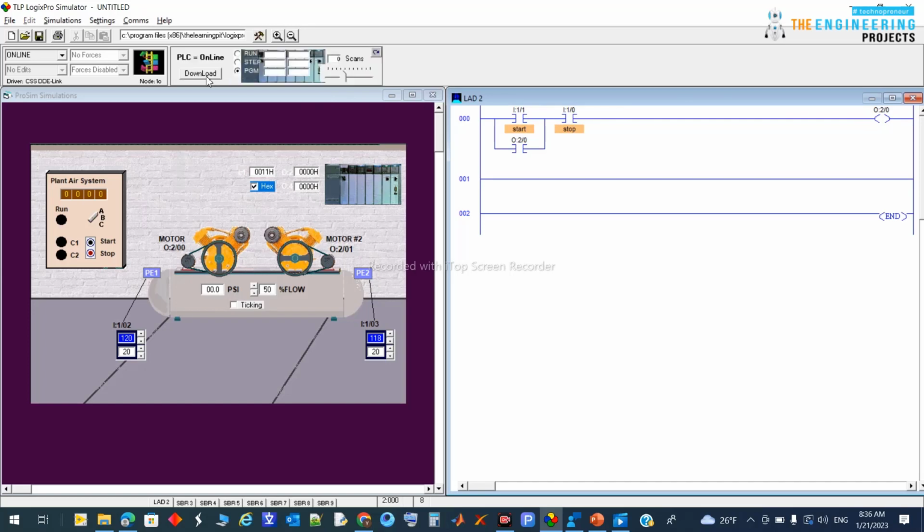But let's run up to this point to see that we missed, for sure, the control for the value of the pressure. If we run it like that, there is no control, so it will continue filling the tank, and the pressure will go above the limit, which might cause a problem to the tank itself, which is very dangerous. So let's try and see. If I press the start button, the compressor is now running, and you can see the tank pressure increasing.